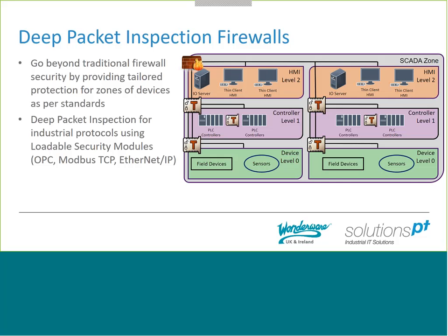So it might be that this is a Modbus network and you only want to allow Modbus traffic through here. So you impose these rules into the device, and it'll enforce them for you. You can use loggers and things to monitor the traffic that tried to go through that device or tried to go through the network, to monitor what's going on. But yeah, a really secure way of securing your architecture.